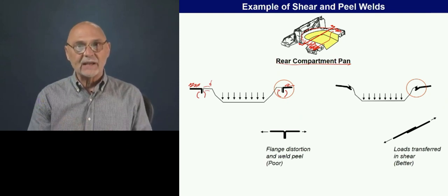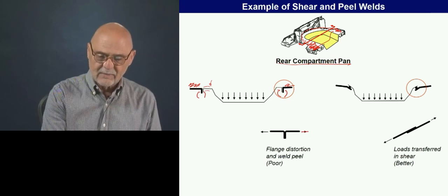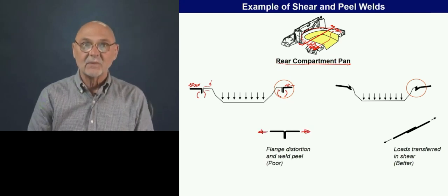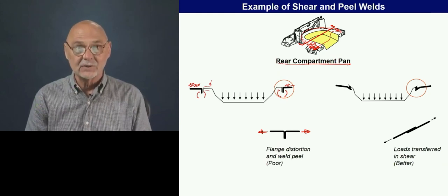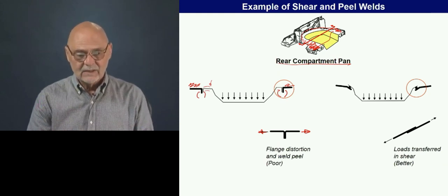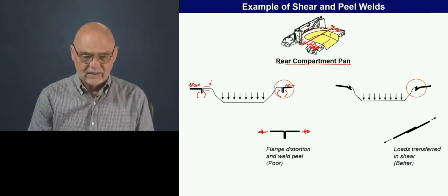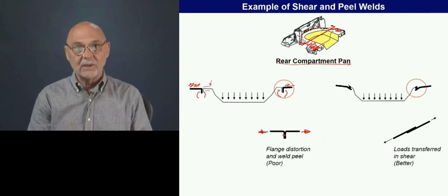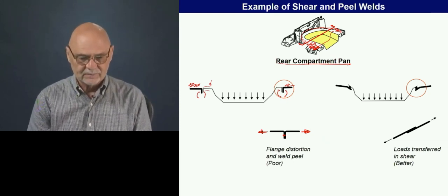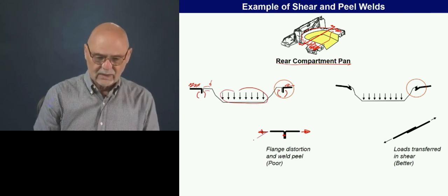Whenever we visualize the loads on sheet metal, we always visualize them as in the plane of the metal. Remember, in the last lecture we talked about how advantageous it is to put the metal in membrane-like loadings rather than bending. So here's the loading condition, and you can see that we're trying to peel those joints apart under a downward load here.